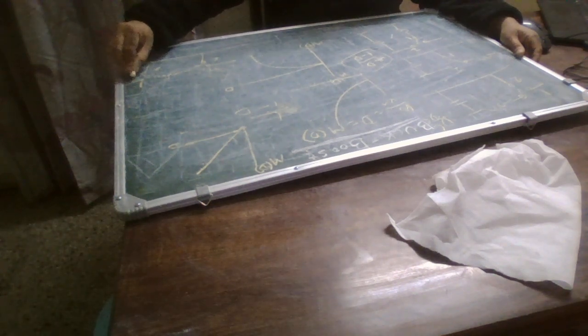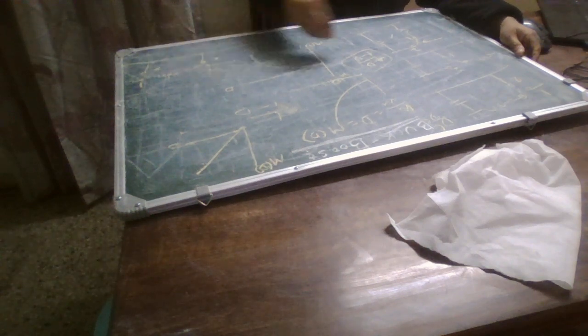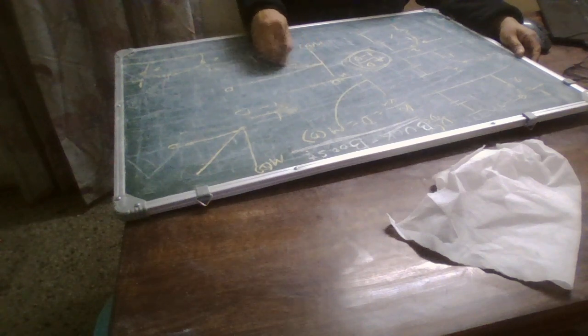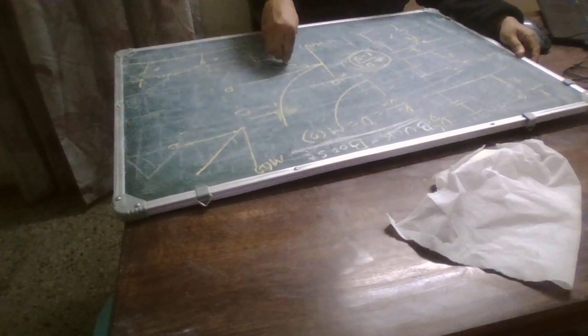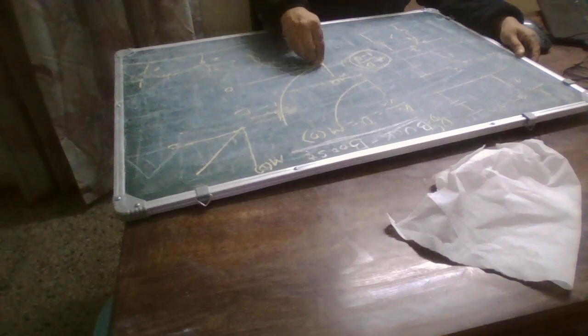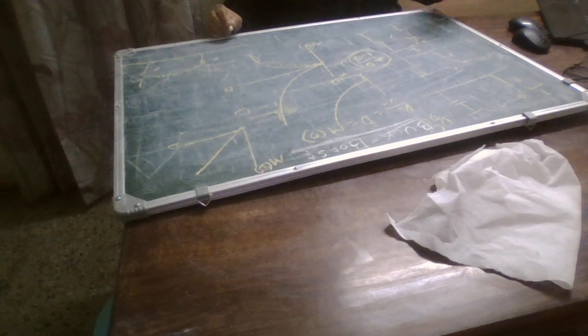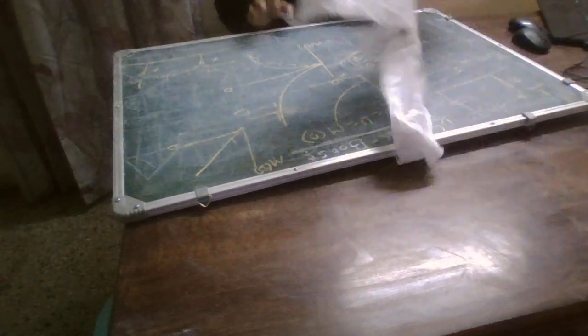This is a non-inverting configuration, therefore the conversion ratio is D upon 1 minus D. Instead of falling, it would be rising here. The difference between the boost and this would be that it starts from 0 here, it does not start from 0 in the boost. So let us first go into the derivation of how the buck boost configuration is cascaded.